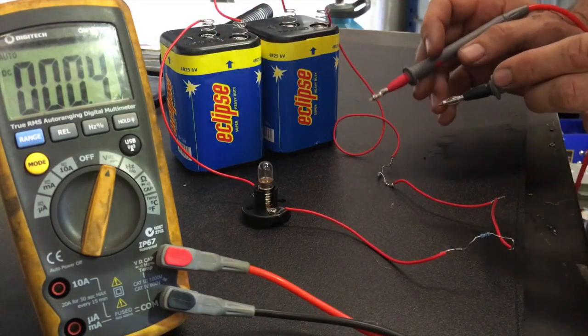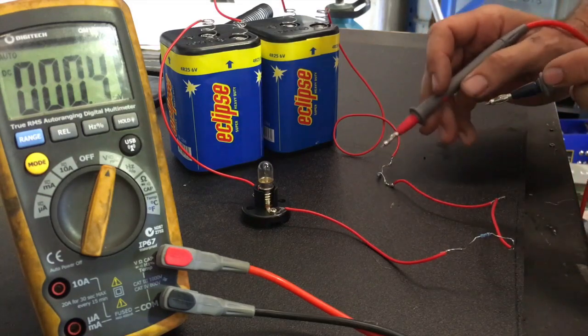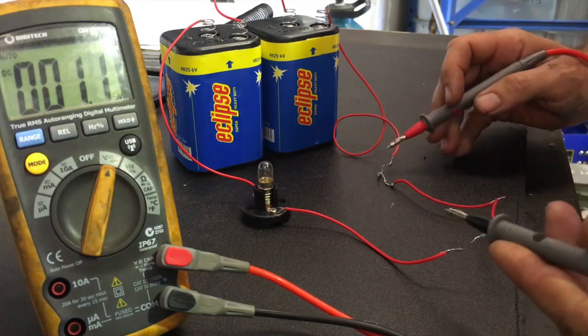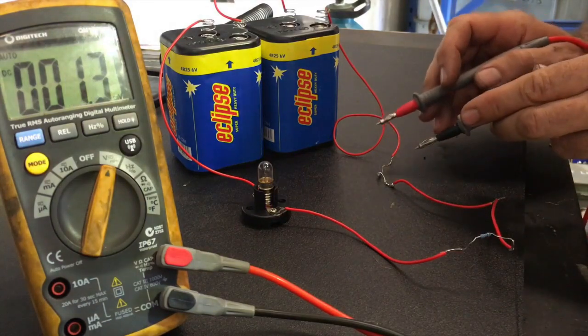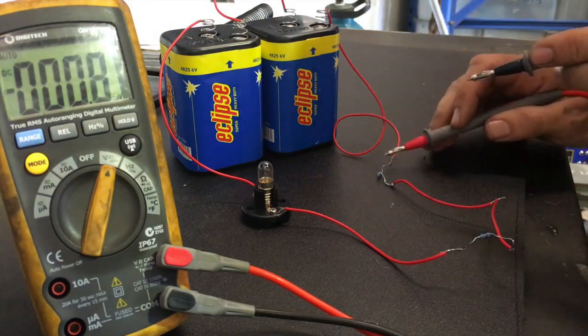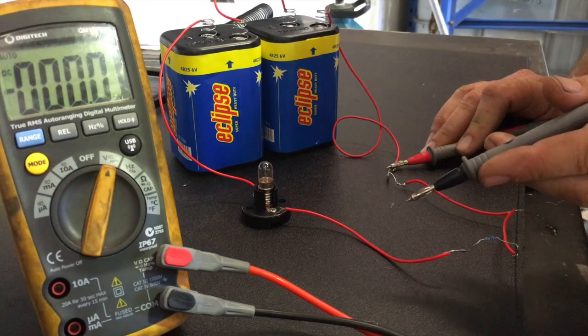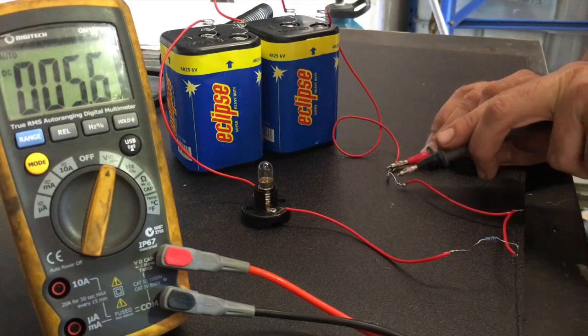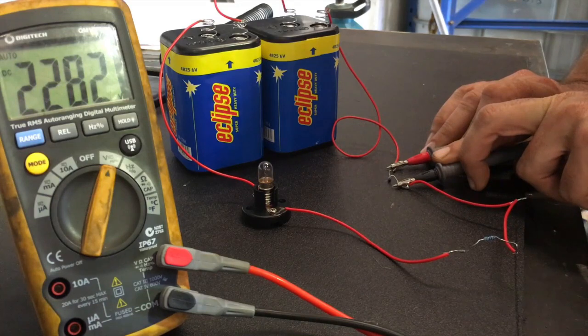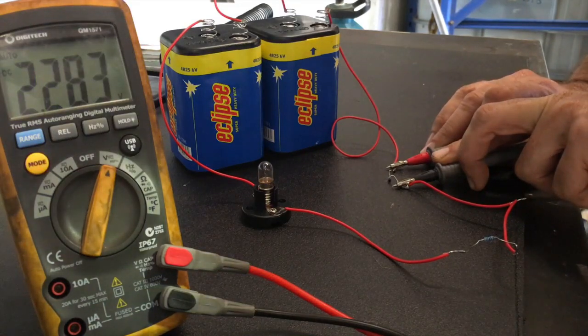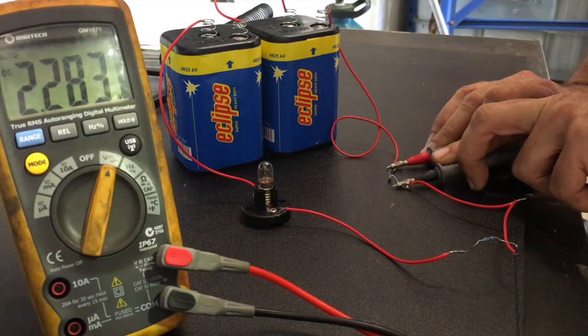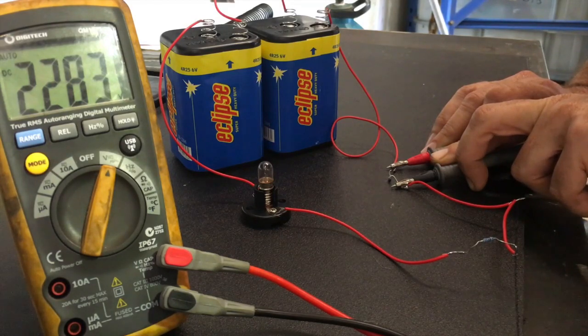To test the voltage drop across a particular part of the circuit, and that could be an individual component or a couple of components together, whatever I want, I simply put the positive lead of my multimeter on the side of the circuit closest to the positive terminal of the battery. Then I put the negative lead from the multimeter on the side of the circuit closest to the negative terminal of the battery. And here you'll see we've got a 2.28. So once again, slightly higher than the theory, mostly due to a bit of a rounding error. But that's the voltage drop across that resistor, pretty much in line with what we calculated using the formula.